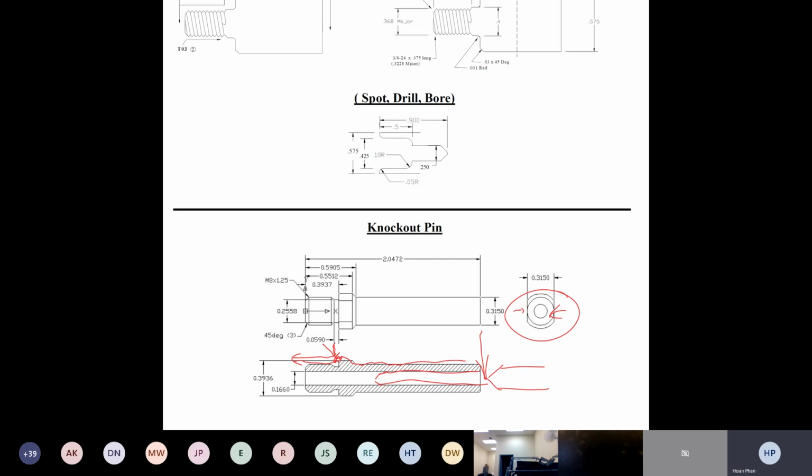And then after that, I don't see that we have any other operation for the main spindle, so I will go ahead and cut it off right here. And that's all the plan for the front side. And on the back side right here, since we know that we machine this side first, we have to plan to get a collet to put in the sub spindle to pick up the parts.